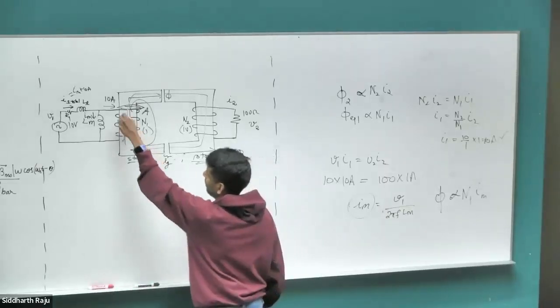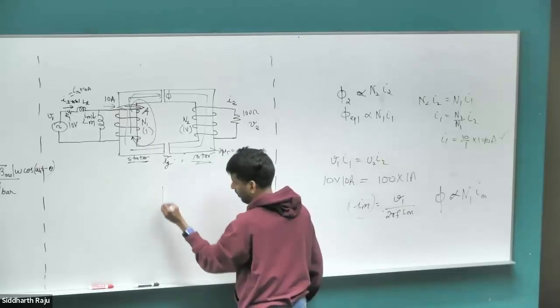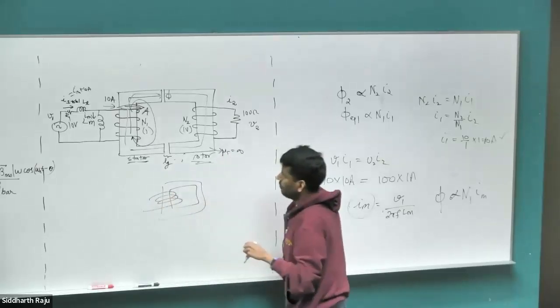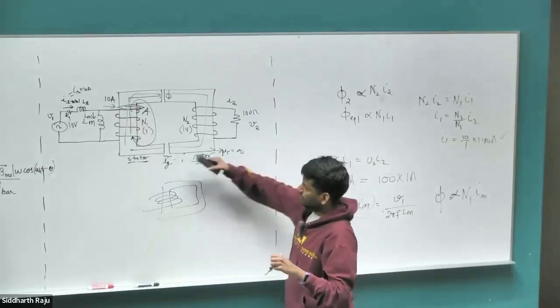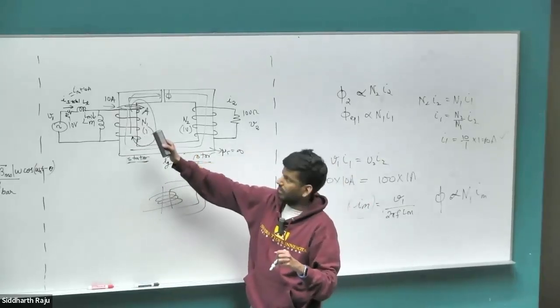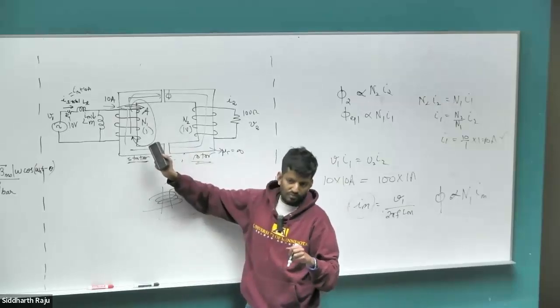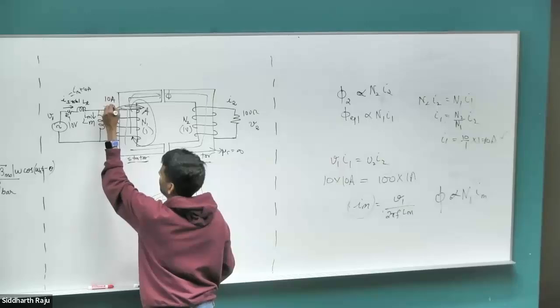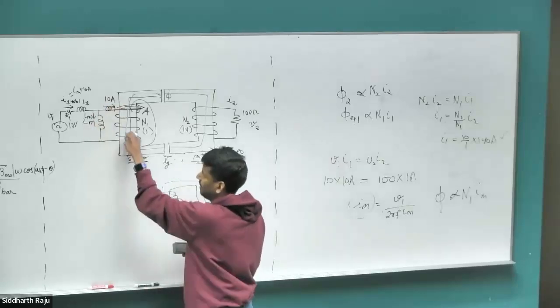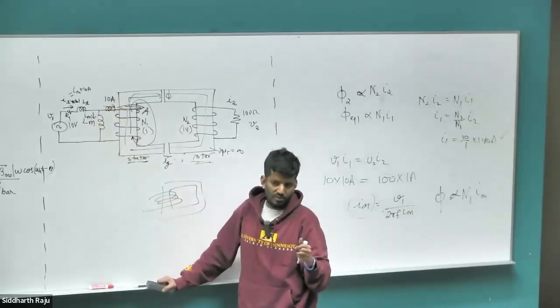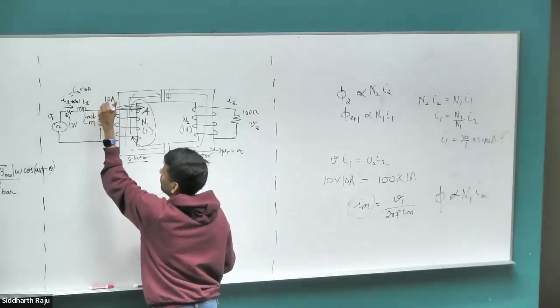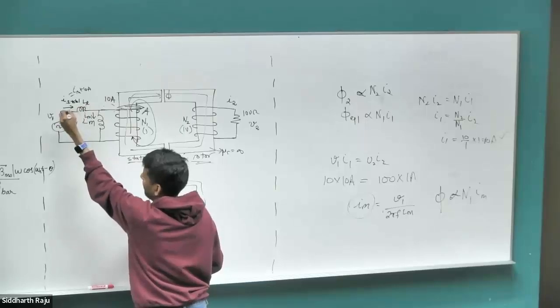So the idea is whatever current flows here, the total current flowing into the transformer, both due to the secondary current as well as due to the magnetizing current, is going to establish a flux, and some component of that net flux is what is flowing out. Right? If you try to put it here, then this component of the current that established the flux to begin with is not captured at all in your drop in the inductance that we have. So we put it on the left,